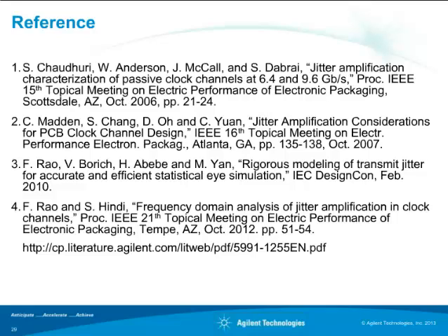Next question is also from Inho. What is the most effective equalization methodology at the receiver to cancel or mitigate jitter impact? Is it a continuous time linear equalizer or a decision feedback equalizer? Any thoughts on mitigation? It depends on what data rate you're talking about. At high data rate above 10 gig, you have to use a combination of both.